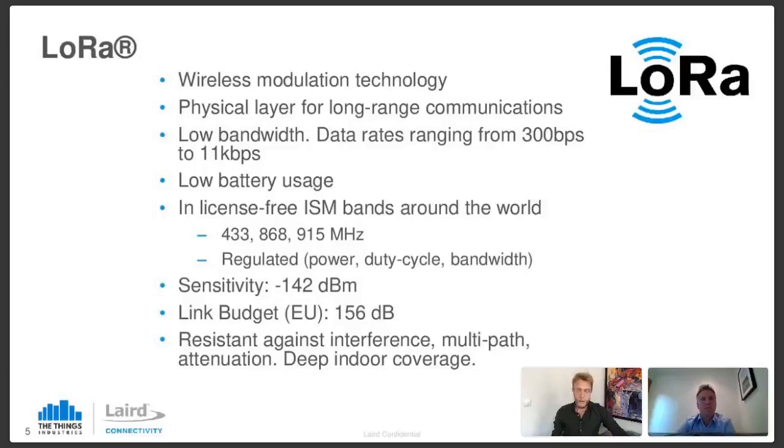When you have a line of sight in outdoor areas, for example, you typically have coverage, even tens of kilometers of range are possible, and anything in between. So it really depends on the terrain. It's sub-gigahertz ISM bands, and that means that you can deploy a LoRaWAN network yourself, so you don't depend on any license for a spectrum. The ISM bands are not harmonized globally, so there are different regions defined also in LoRaWAN, which you need to be aware of, but this is a problem that is actually solved by gateway and device vendors.